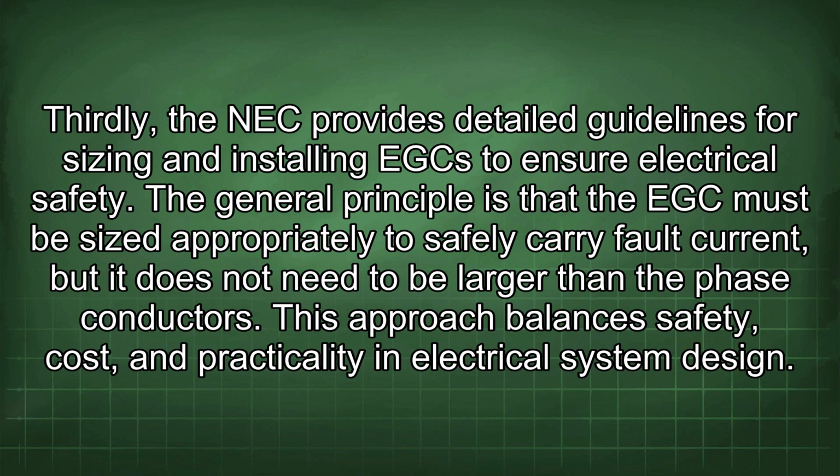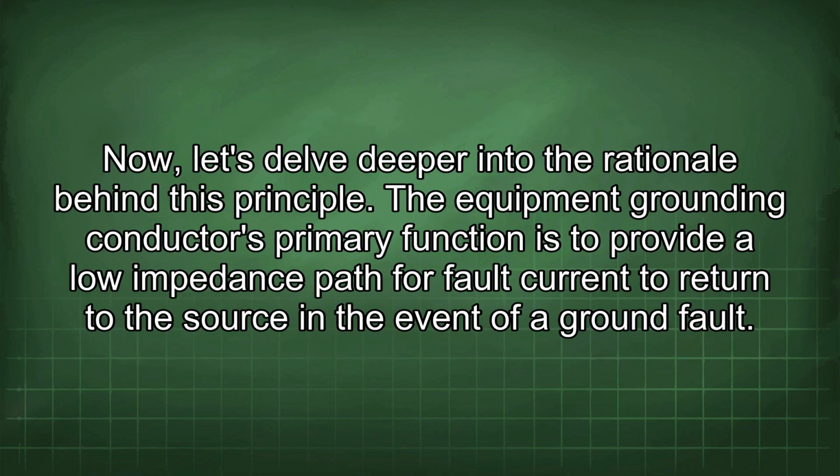The general principle is that the EGC must be sized appropriately to safely carry fault current, but it does not need to be larger than the phase conductors. This approach balances safety, cost, and practicality in electrical system design. Now let's delve deeper into the rationale behind this principle.